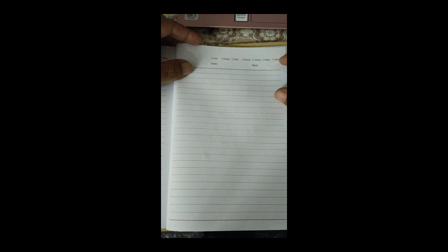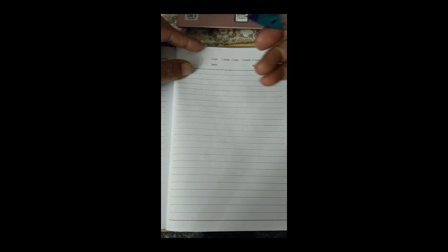Okay, we continue with the question. Water enters at 5 megapascal and 20 degrees Celsius. Determine the minimum mass flux of the water so that the water does not completely vaporize. Okay, completely vaporize, which means T sat. Neglect the pressure drop through the heat exchanger, and calculate the rate of heat transfer.